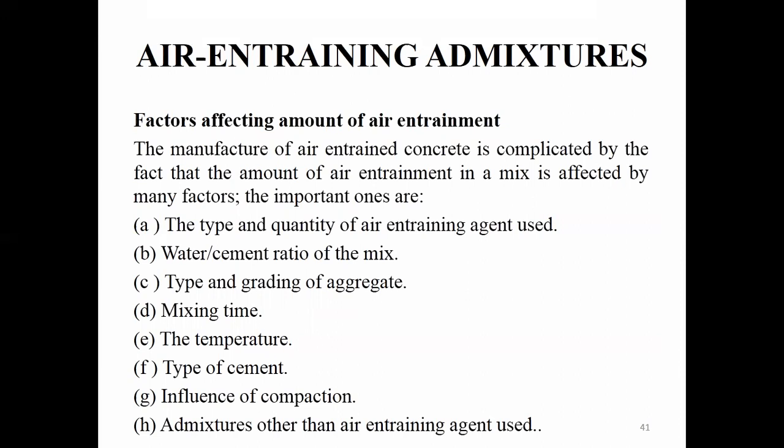One is the type and the quantity of the air entraining agent, the water cement ratio of the concrete mix, the grading of the aggregate and the type of aggregate you are going to use, the mixing time, the temperature of the environment in which you are going to use this air entrained concrete, and the type of cement.